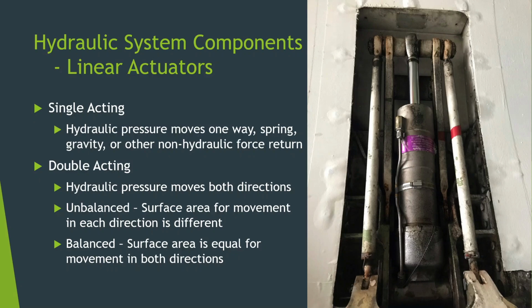So this is the pressure here times a surface area, which is given in inches squared. That gives us our force. The inches squared cancel out, and that gives us just a straight up force in pounds.